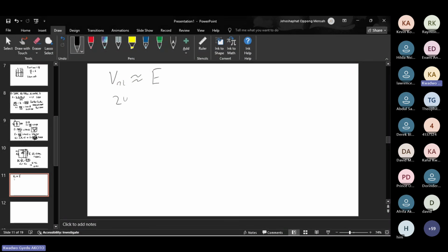And our no load voltage is 240. So 240 can be made equal to 435 IF all on 193 plus IF to find our no load IF. So our no load IF is going to be equal to 2.375 amps, right?